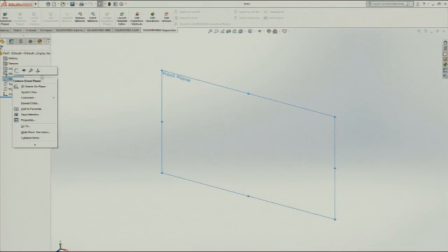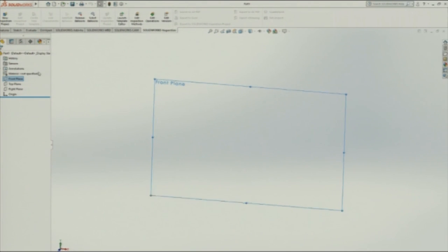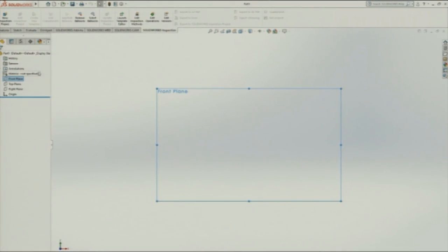Now, I need to select a plane again. Immediately I will make components for the flange coupling. A flange coupling is used to connect two shafts which are concentric. So, we need two flanges which are identical. Let me consider the shaft diameter is 20 mm. The 20 mm diameter shaft has to be fixed using this flange coupling.